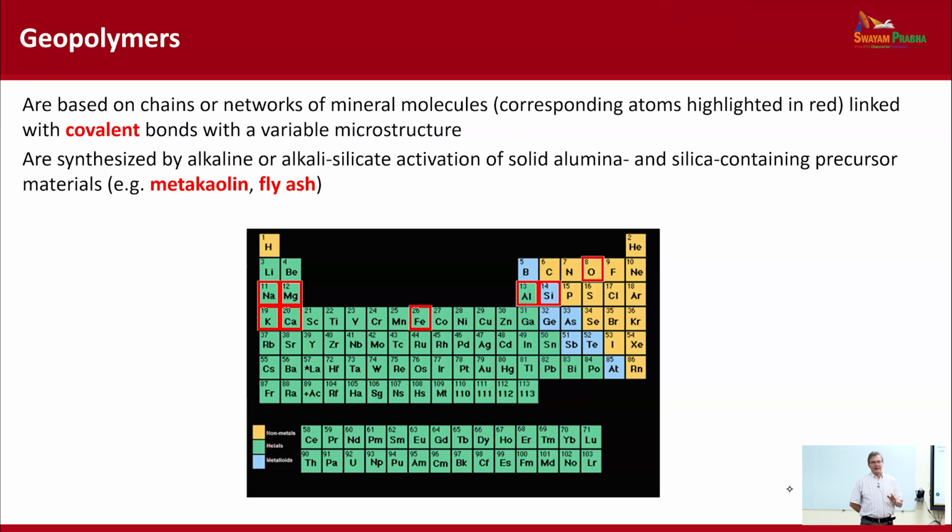It was given by Dr. Davidovits, a French scientist, who came up with this idea, but his background was polymers, and he called these materials geopolymers because, as you will see, they have a structure that is similar to the structure of a reticulated polymer, and they form by condensation reactions, meaning that in one sense they polymerize. And they call them gel, because of course they are inorganic.